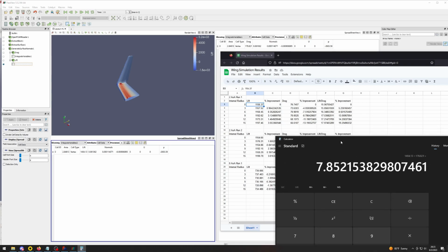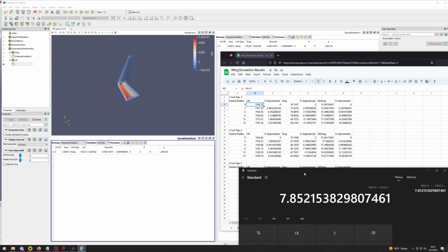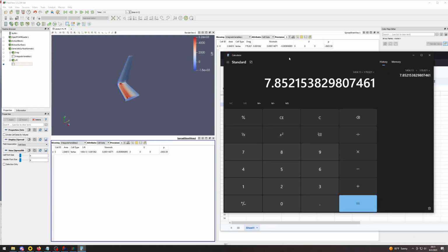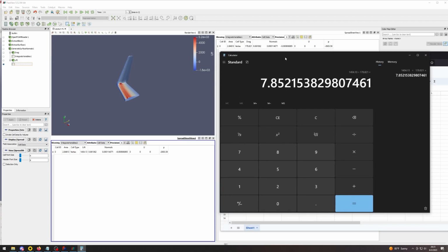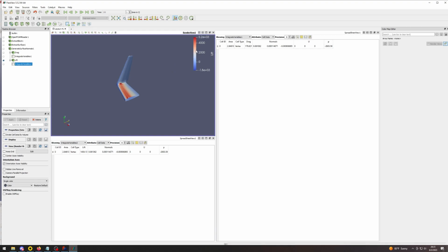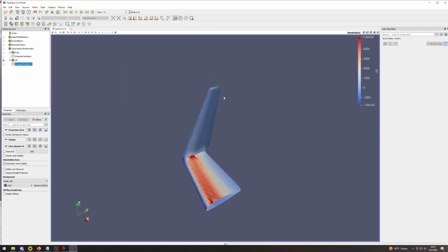You can see that is significantly less than what we had before, but the main reason for that is we had a pretty aggressive angle of attack for this speed of the airplane. This was the kind of lift to drag ratio we would expect while doing something like a steep turn or a more aggressive maneuver. And yeah, that makes sense. So there you go. That is how you can get the lift and drag, and to get rid of these, we can put those away. And that's how you can do your own computational fluid dynamics study if you really want to.